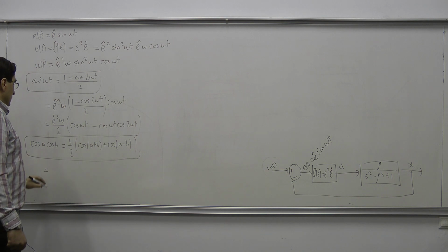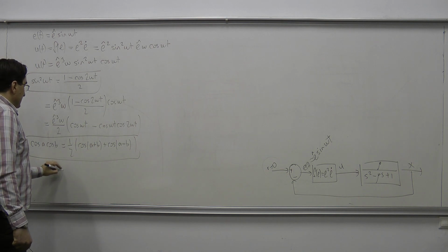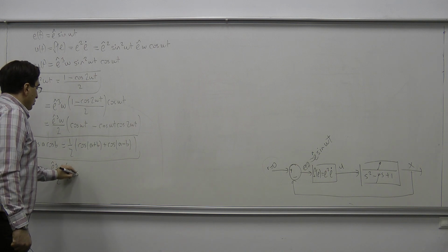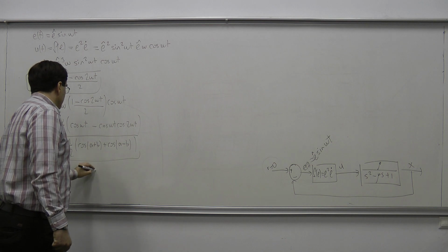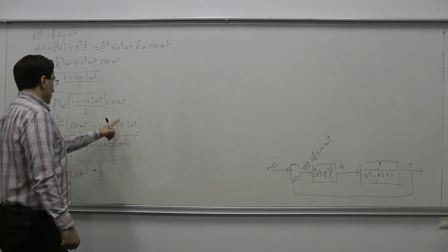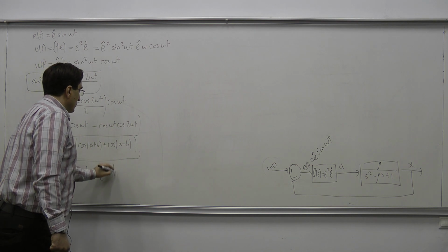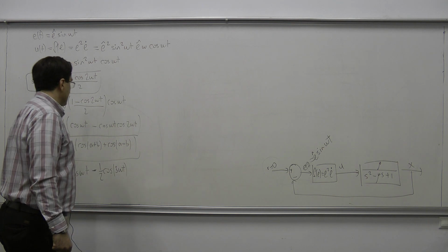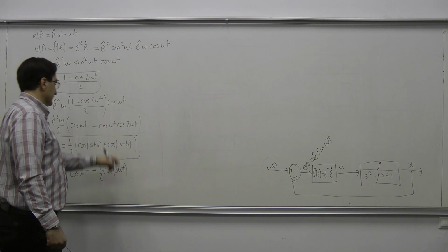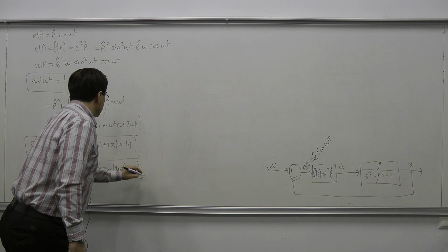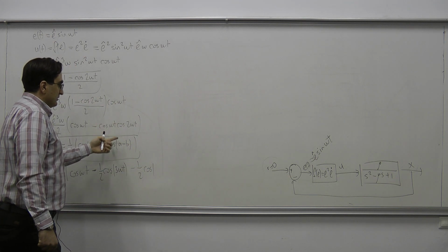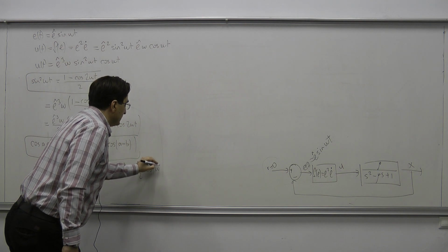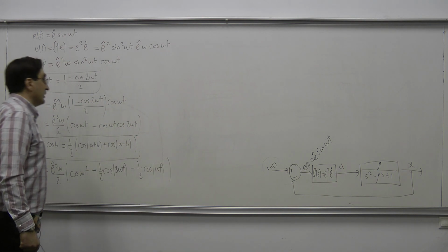All right? So that is E hat cube omega over 2, so cosine omega t here, and instead of this I will write minus 1 over 2 cosine sum, cosine 3 omega t, and cosine difference, minus 1 over 2 cosine of the difference, which is minus omega t, but minus would not matter in cosine, so I would just write this.